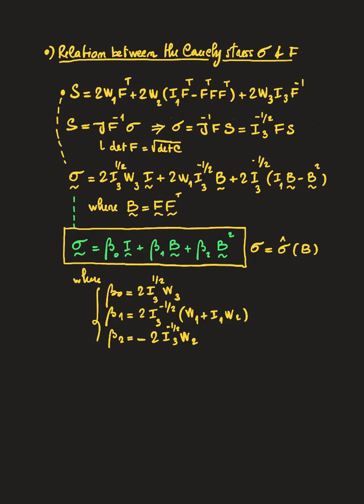For this reason, in fluids it is usual to employ expressions of the following type. I don't know if you have ever heard of the so-called Navier-Stokes equations. Well, Navier-Stokes equations refer to the behavior of viscous fluids, and in fact in those fluids the state of stress is defined on the current configuration. Of course, in fluids things become more complicated because since there is no reference configuration, the energy cannot depend on a deformation, but it will depend on the velocity. But this is just to highlight the importance of working in a current configuration.